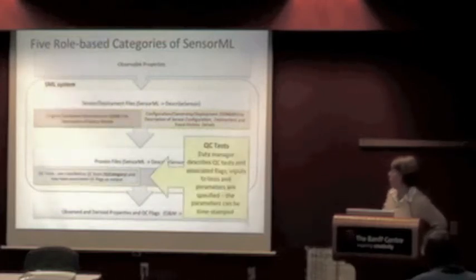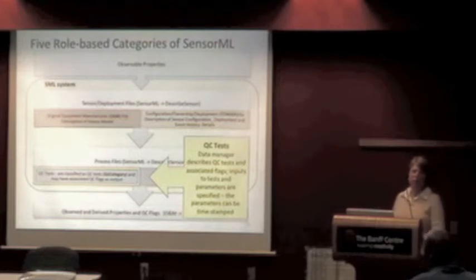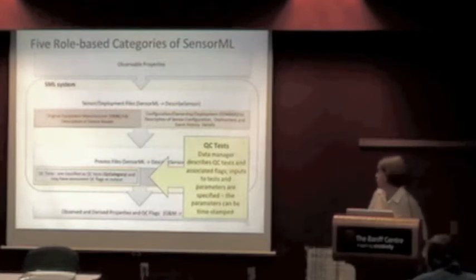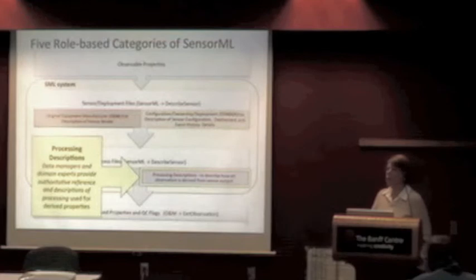And then we have a QC flag category for processing. So I send it to the NDVC and they can look for my QC flags. Instead of throwing out data that might be a tsunami, they get it, there's an alert, and either I know I have to go out and clean the sensor faces, or they know they have an event to deal with, and so do I. And then again, as I mentioned before, processing so that people know how you got your derived property.